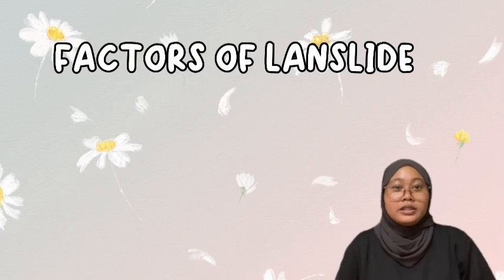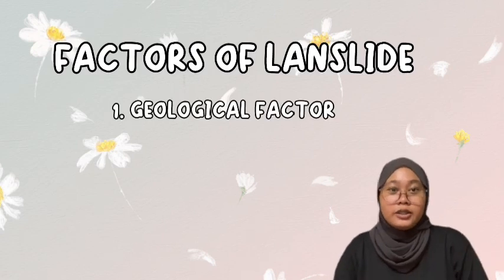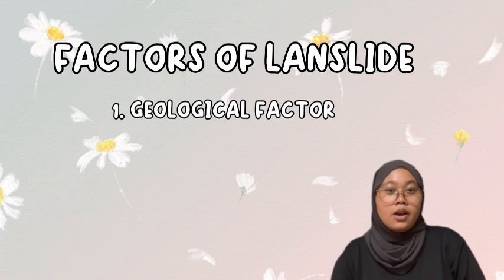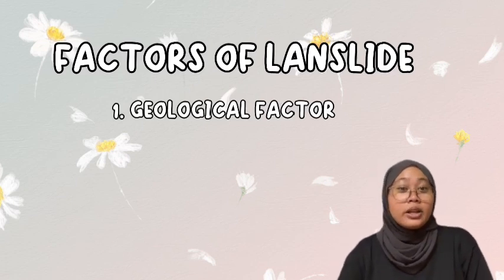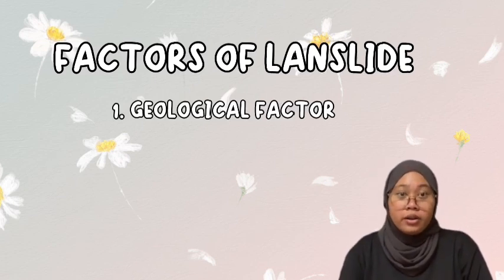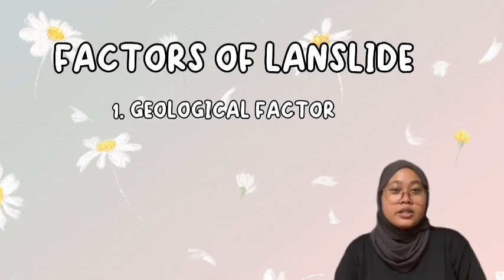There are a few factors of landslide. The first one is geological factors. Rock type in an area influences its susceptibility to landslide. Highly fractured or weathered rocks may have reduced cohesion, making them more prone to slope failure.